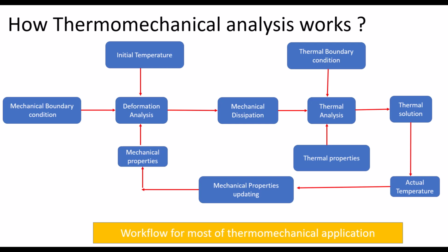Now let's talk about the workflow. I want to highlight that this workflow was created keeping in mind mechanical dissipation. If only thermal stress is concerned, then we can start from this portion. First we are going to perform the thermal analysis. We will get the actual temperature, so if the mechanical properties are a function of temperature, those will get updated and then we will solve the structural simulation.